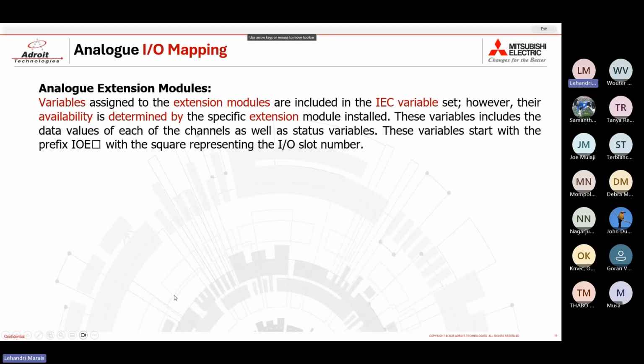Now, as I said, those variables are IEC variables or part of the IEC objects. Now, for the analog extension modules, there's also a set of variables that are available within the IEC variables. These start with the prefix of IOE and then whatever number IO slot.